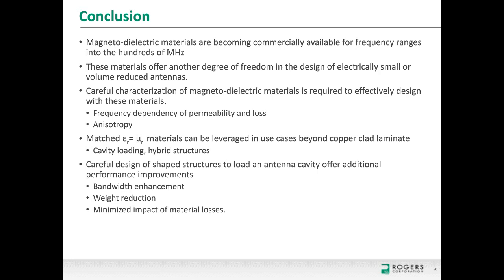Next question, can you discuss any differences in drilling and plating of this material compared to typical PCB laminates? So in this case, the material that Rogers has is a PTFE matrix, so it'll drill and plate just like a standard PTFE material. If you're familiar with our Duroid materials, RT/duroid 6000, our magneto-dielectric material will behave a lot like that.